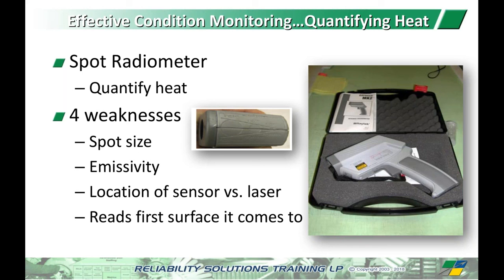If your system's running hot, there's a reason for it. Obviously, if it has a cooler on it and the cooler's plugged, then that's a good reason. But in many cases, it's got a cooler on it, but we decide that the designer didn't know how to design properly, and the cooler's inadequate, so we add an extra cooler instead of doing what we should do, which is trying to find out where the heat's coming from.